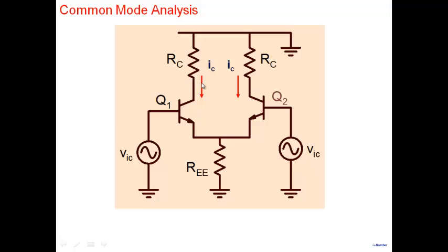The same small signal collector current will flow here and same will flow here. Exactly the currents would be the same. These two currents that you see here and the same emitter current would also flow here because of symmetry. Whatever emitter current is here, same emitter current would flow here. And these two emitter currents would add up, and twice the emitter current of one individual transistor will flow through RE. Okay. All right. So this is what we have.